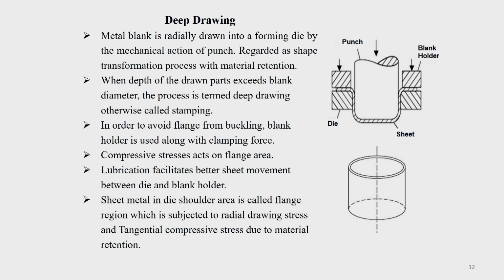Another sheet metal operation which is extensively used is deep drawing. If you look at most household items, tumblers, steel glasses and other things, they are made by the deep drawing operation. Any part with deep recessed features is made by deep drawing.